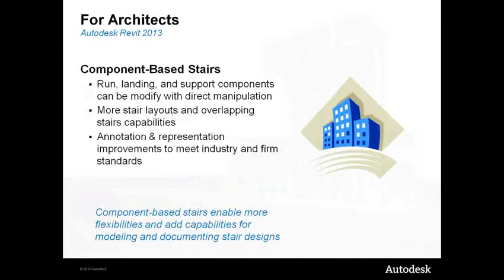Component-based stairs provides capability to assemble a stair using individual run, landing, and support components. Each run and landing component can be modified using direct manipulation controls. You can preview the stair in 3D as you sketch. Component-based stairs allows overlapping stairs to be created, as well as more stairs layouts including winder stairs.